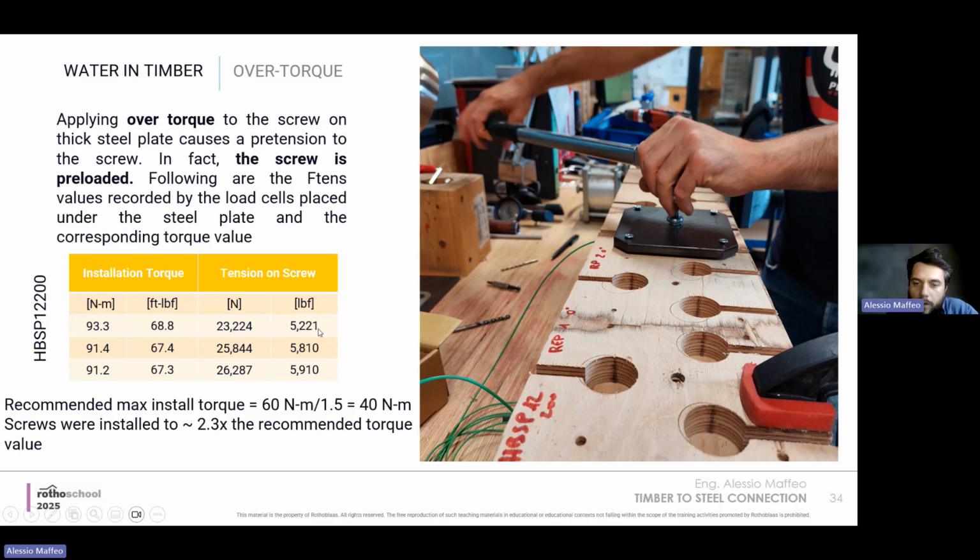So the amount of actual stress that you get due to the installation is pretty high. This amount of stress is easily the same amount of stress that the screw itself can withstand. If you check how much this stress is compared to the steel tensile resistance of the fastener, you will see that just with the wrong installation, you are already using all of the tensile resistance of the fastener itself.